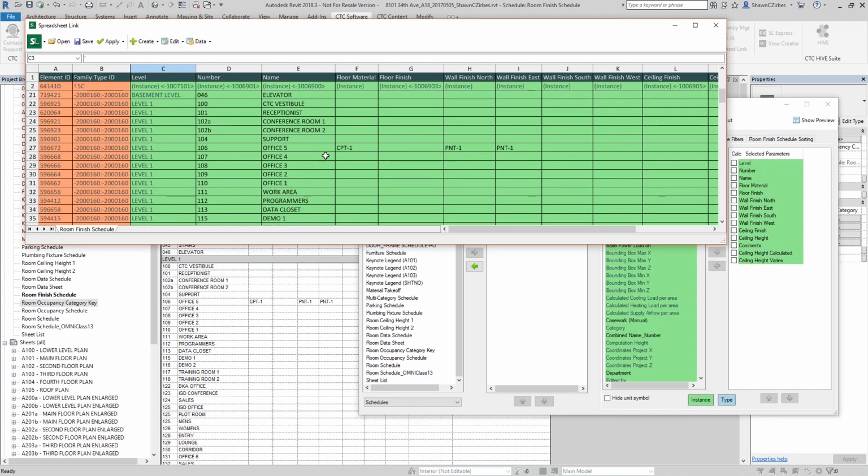So you can see right here, I've got the same offices, same order of the rooms. Now what I want to do is take my paint right here, and I want to copy this across. I'm just going to use Excel-like autofill to drag that little bottom grip across, and it fills it in all the way across. And maybe I want an accent wall in here on the west wall or something. I don't know. Do whatever you want. Maybe I also want to take this and autofill this down.